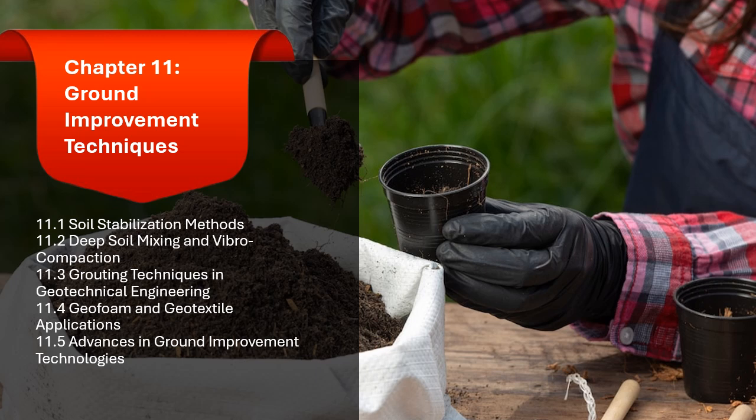1.1.2.1.2 Applications of deep soil mixing. Foundation improvement. DSM is particularly useful for improving the bearing capacity of soils for foundations. The process is used for soft soils, loose sands, silts, or highly compressible clays that would otherwise not support heavy structures.